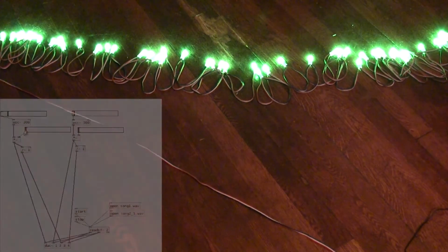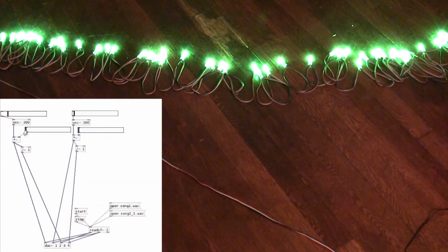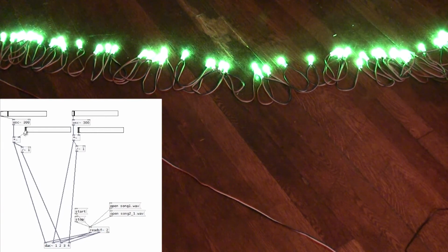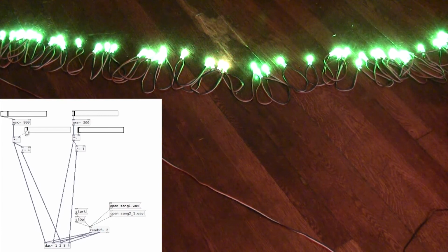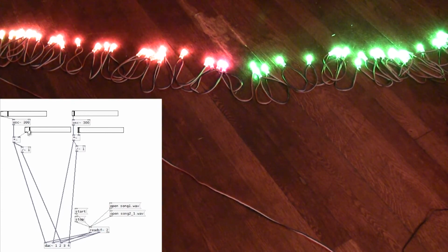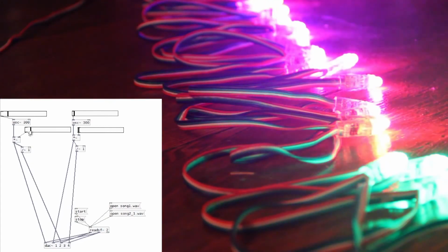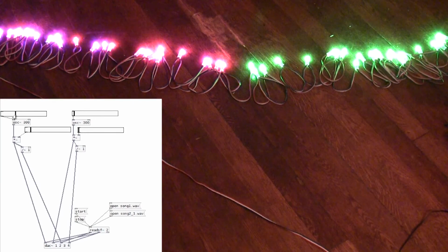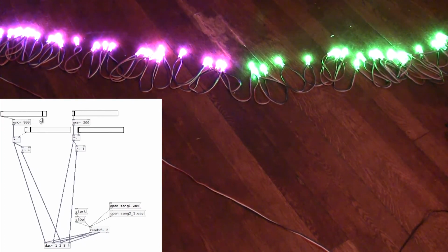So what I've done now is I've put together a quick little program on my computer in a programming language called Pure Data, which is a graphical programming language that simply outputs a frequency on my audio channels. So right now I have a frequency set, and I can crank up the amplitude a little bit, and sure enough you can actually see the sine wave propagating across the channel of LEDs. It's really cool. And as I increase or decrease the frequency, you can see we start to get an aliasing effect, and if I increase the frequency enough, it becomes a basically solid color.